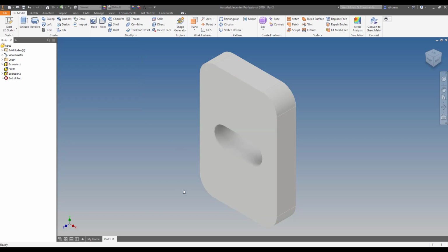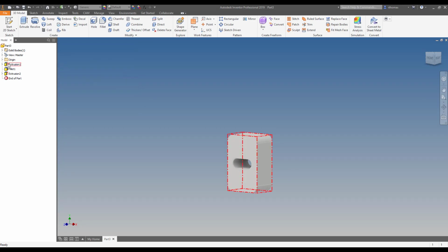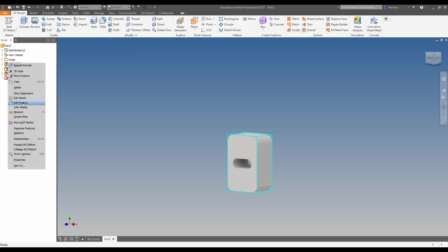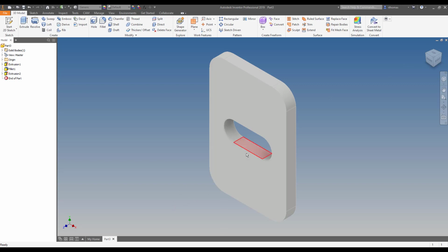So now, I'll just turn it a little bit. That slot always goes all the way through, irrespective of how big I make the part. So I'm just going to return that back to its original 10 millimeters. Okay, so it's just something you need to bear in mind when we're talking about holes and slots. Just pay attention to whether they need to be a set depth or all the way through, and if they do, make sure you enter the appropriate depth when you do that.